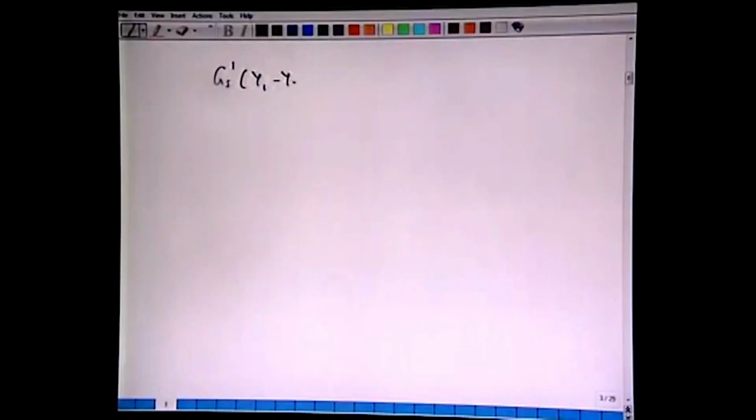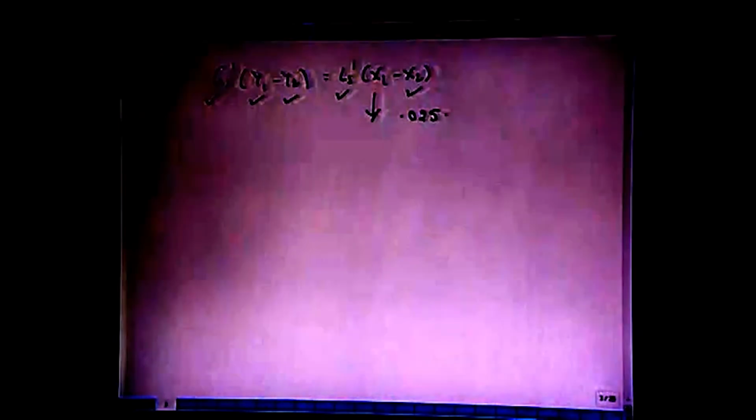Again here one can take this curve and write the operating curve expression as GS prime (y1 minus y2) equals LS prime (x1 minus x2). GS prime is given to us, y1 and y2 are known to us. LS prime, we know the operating value, 30 kilomole per hour per meter square. X2 is 0, so x1 can be solved here to obtain the same as what we obtained graphically, 0.02588.